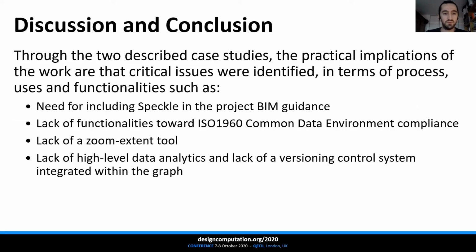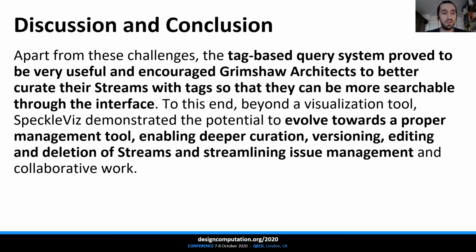And through the two described case studies, the practical implications of the work are that critical issues were identified in terms of process use and functionalities, such as the need to include Speckle in the project BIM guidance, lack of functionalities towards ISO CDE compliance, lack of a zoom extend tool, lack of high-level data analytics, and also a versioning control system integrated within the graph.